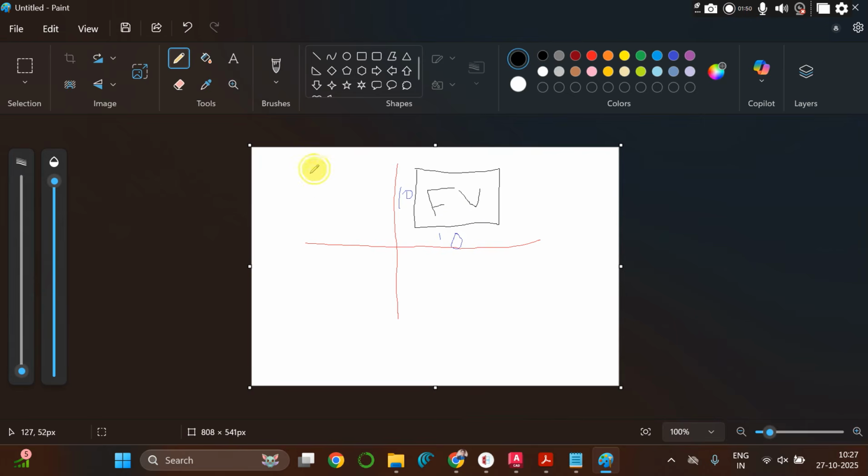Similarly, now in this figure there is a right hand side view. So this is RHSV, right hand side view. This value is 10. This is also 10. Okay, and then there is a top view. Again, this gap is of 10 mm. Okay, so initially what I will do, I will make a complete box.